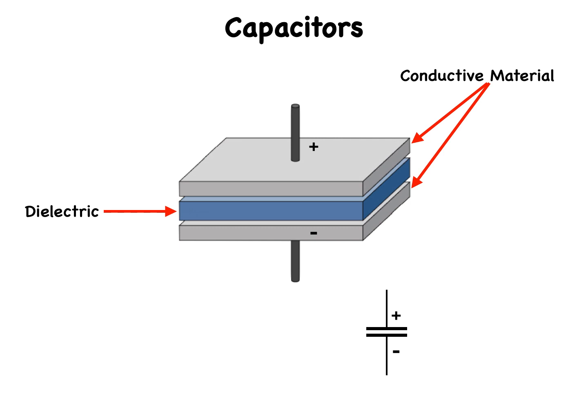When you see the plus sign, you know that the component is polarized, and therefore, that you must connect it to the remainder of the circuit in observance of the proper polarity. That means the positive capacitor electrode must go to the more positive DC voltage point in the circuit, and the other electrode must go to the more negative DC voltage point in the circuit.